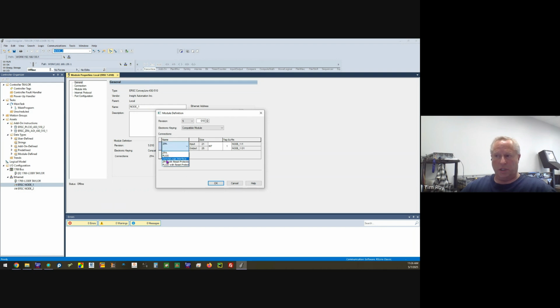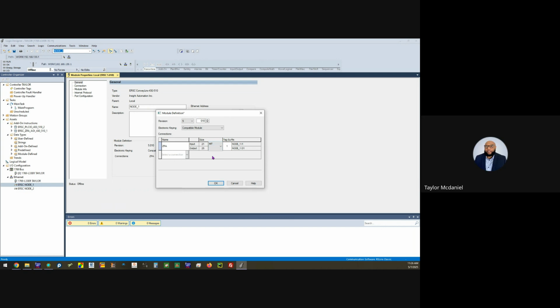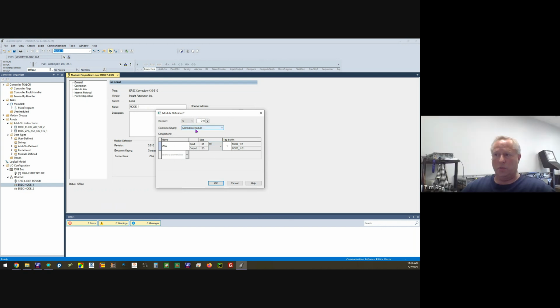This is where you select how to use the module. I don't think with your version you have the selection because it's either ZPA or PLC mode. Be sure under size, you select integer. You could either use compatible module or disable the keying. Then you can press OK. Yes.